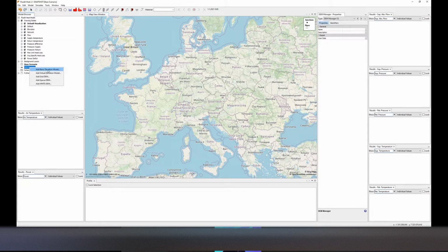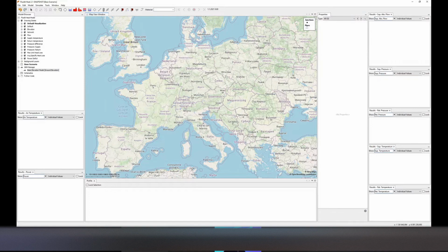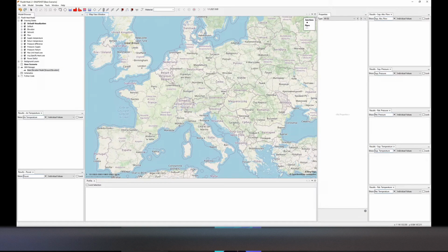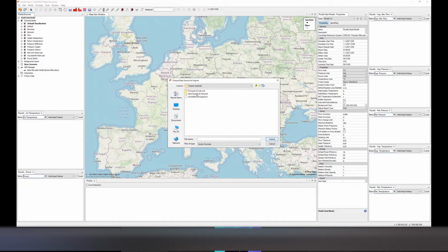One other thing that I do want to set immediately is a digital elevation model. I will be using now for this purpose Open Topography DEM, NASA DEM Global. In our latest software, we have global digital elevation models that can help a lot when working. Also, you might want to pay attention to the CRS, Coordinate Reference System, but I will just be working with WGS 84 for now.